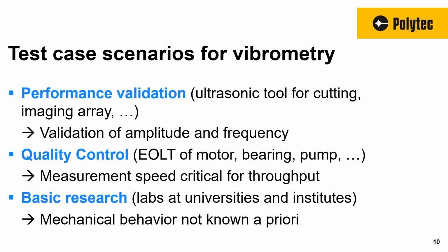When it comes to performance validation, as in the case for ultrasonic cutting tools, imaging arrays, or ultrasonic welding tools, the goal is to validate the amplitude and the frequency. Typically the amplitude is fairly high, so there's no need for a very high sensitivity vibrometer for this application.